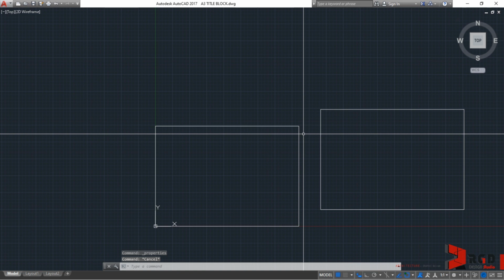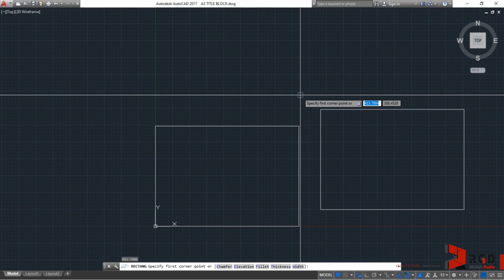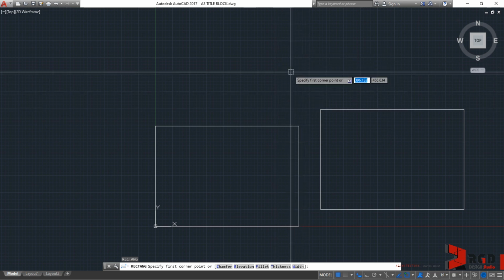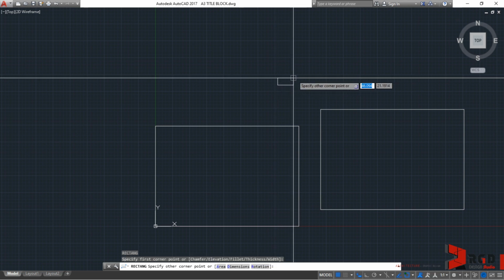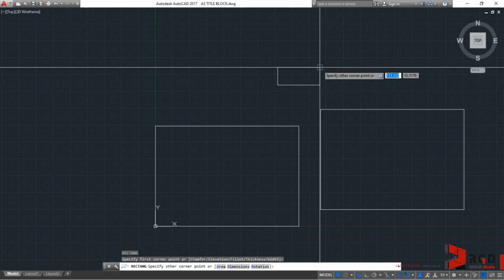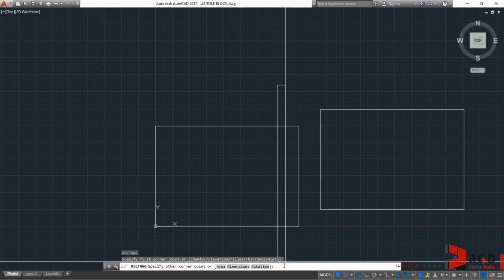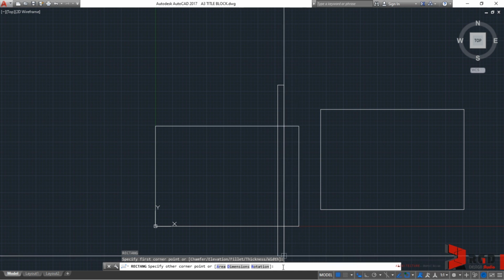And let's create another rectangle. So this is how we practice in AutoCAD, by repetitive commands, and that's the way you get acquainted with the commands. So type REC again and then enter. Again, for the first point, click anywhere again on your drawing area. So I'll just click here, and this time, instead of typing directly on my dynamic input, I'll type on the command line itself. So I'll hover my cursor towards the command line and then click on the command line and type my coordinates. So I'll type for the second corner, 420,